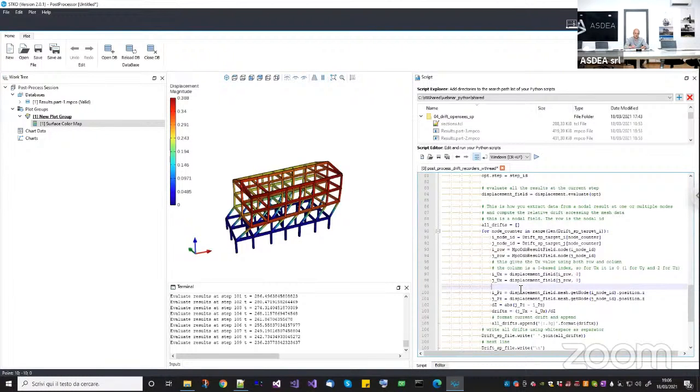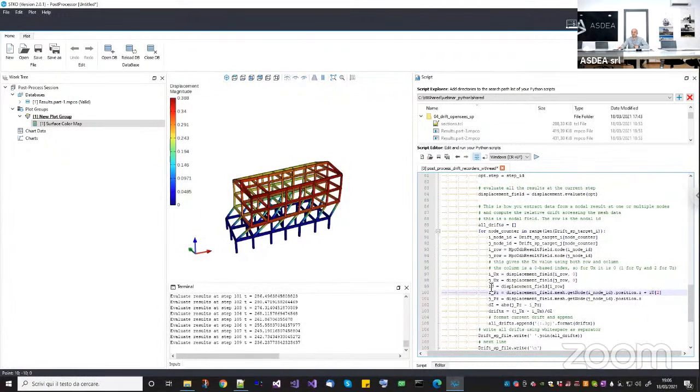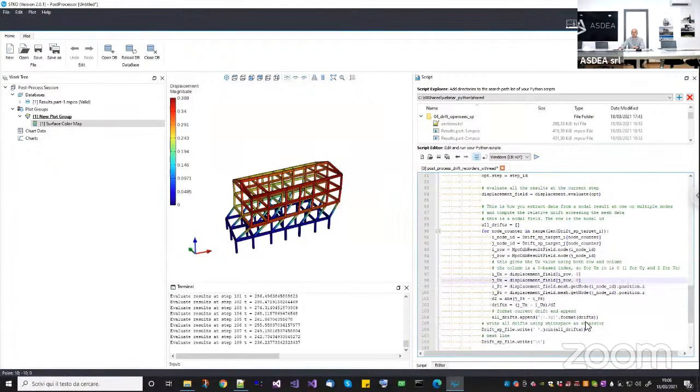If you want the total displacement, like EU is equal to displacement field, and you put just the row, okay? If you put just the row, it will give you the entire row, which are 3 components, X, Y, Z, and then you can compute this deformed configuration as this one plus EU2, which is the Z component of this vector. So here you have the Z component of the deformed configuration, okay? So it's up to you if you want the deformed or undeformed configuration. Now, since we are working in small displacements, I don't need the deformed configuration, okay?